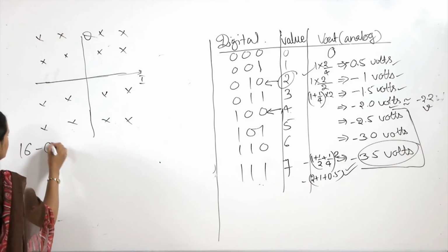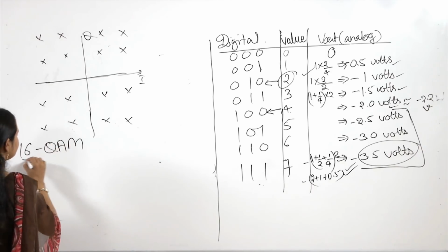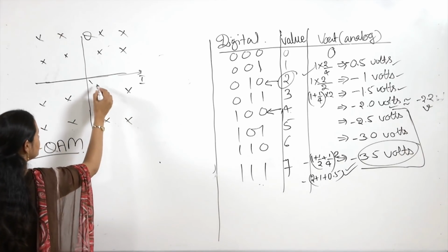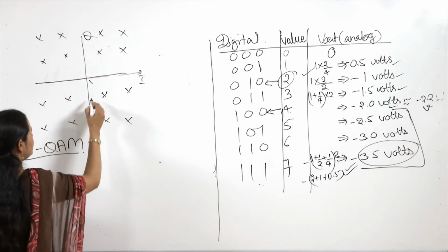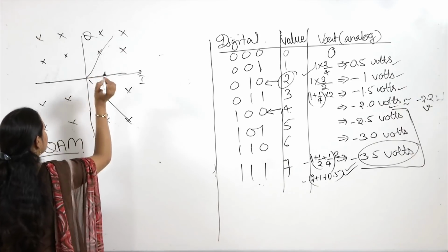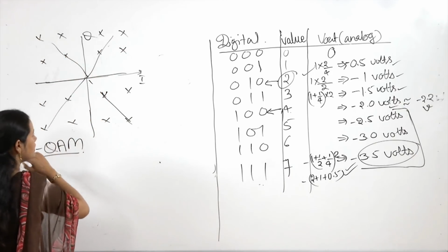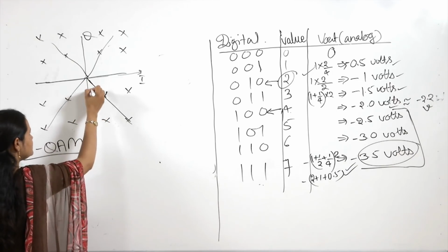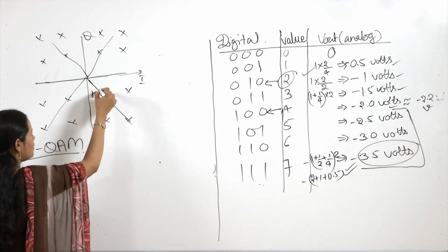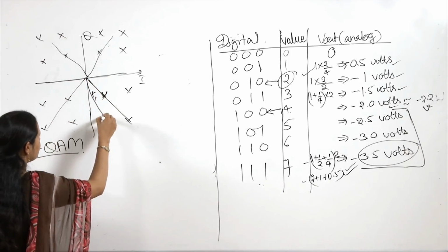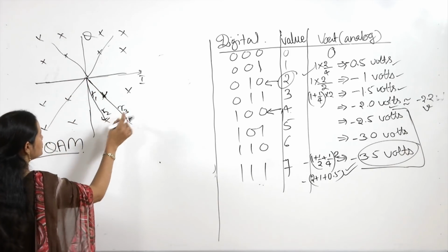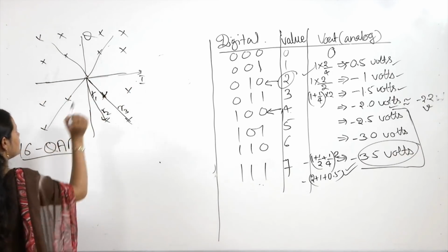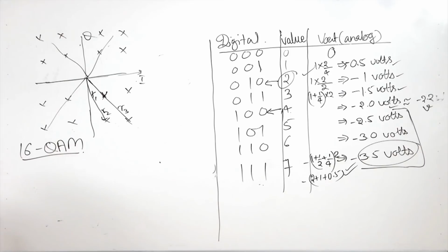QAM. So 16 QAM modulation actually has phase locations here, rotations, right, meaning in this direction, that direction, in that direction, in that direction, as well as amplitude modulation, because some of them have this much R and some of them have a separate R value. So amplitude modulation as well as phase modulation is there, and basically the data in the constellation diagram looks like this.